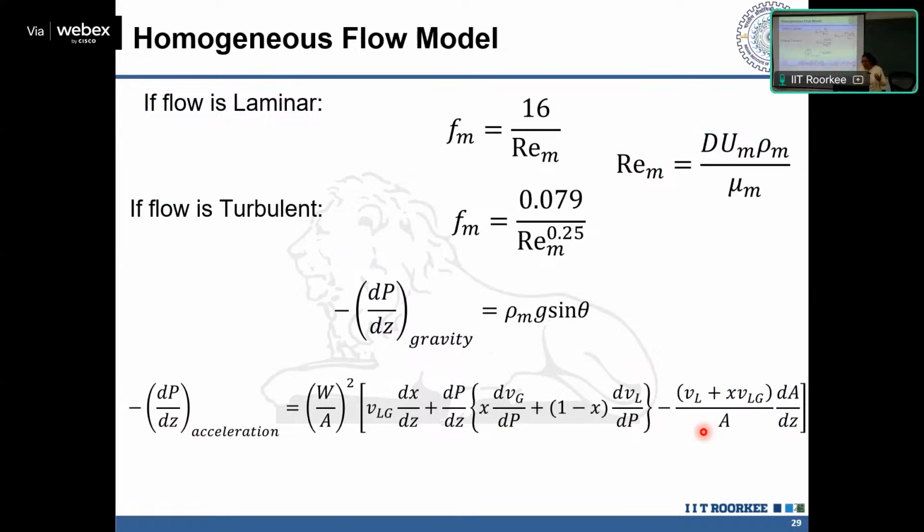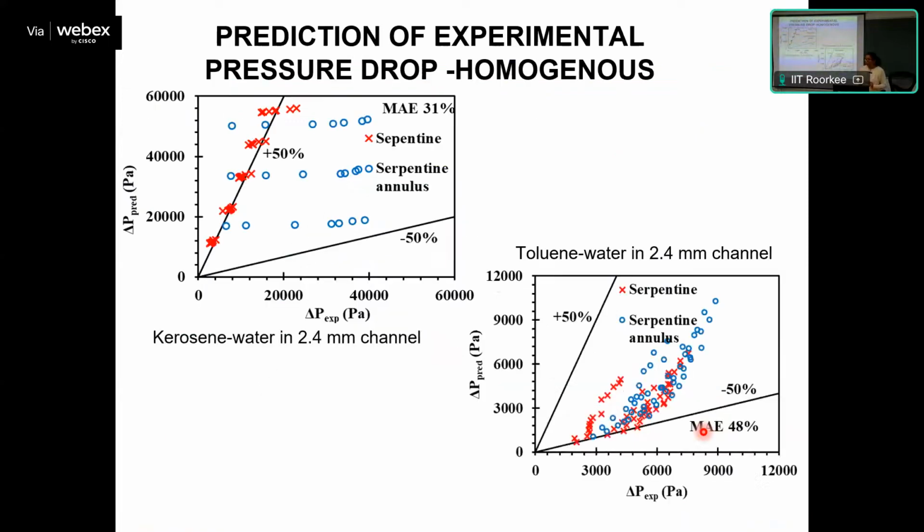So in most cases, if you are dealing with no change of pressure, no change of phases and a straight tube, then this equation becomes simpler. Further, you have friction and gravity only to calculate, and mostly it is the frictional one that we estimate. So this model was developed for macro geometries, working perfectly fine for bubbly, dispersed flow in macro geometries. But is it working fine for miniature geometries also? We have checked this and observed, no.